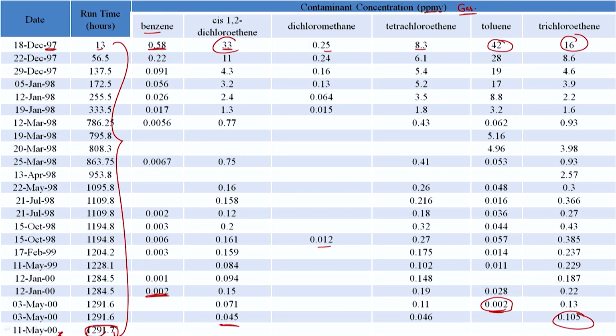Initially, when the concentration is high, what is going to happen if you introduce fresh or uncontaminated air in contact with contaminated groundwater? More of the contaminant will be released. But over time, the concentration in the gas or the water will come down, but it is not decreased to such a level that it is safe enough or has met the standards. And because the concentration is relatively low, you will now need to pump a lot of gas to be able to remove this relatively little mass of the contaminant.